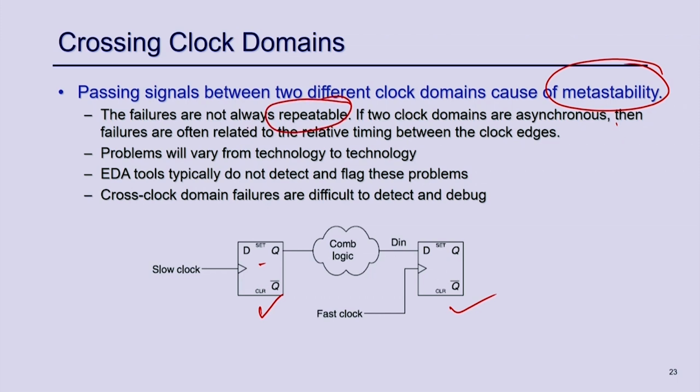It is not repeatable in the sense that it may vary with technology. It may happen that in some particular FPGA architecture it is not happening because of the delay of that particular clock or the devices and some parameters, but in a much faster architecture this might arise.